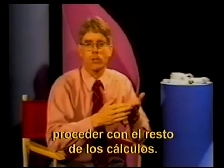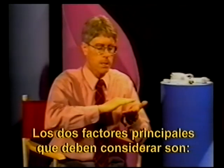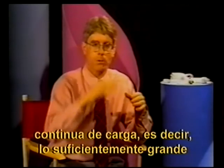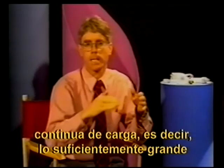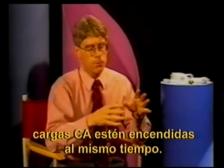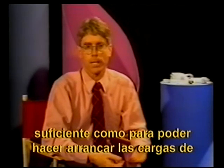The two main factors that you have to consider are choosing an inverter that can meet your continuous load demand. In other words, one large enough to handle the situation where all of your AC loads were on at the same time. And then also an inverter that can surge enough to start your heaviest starting load.